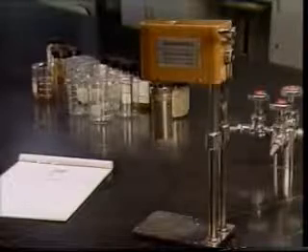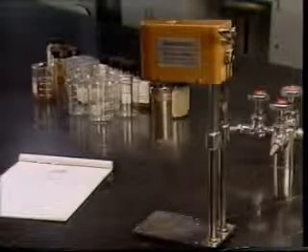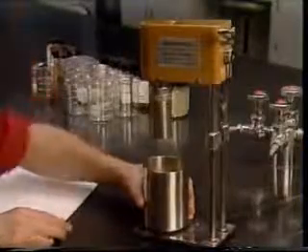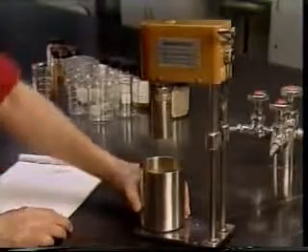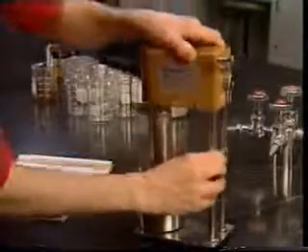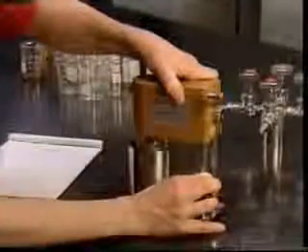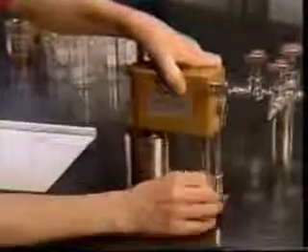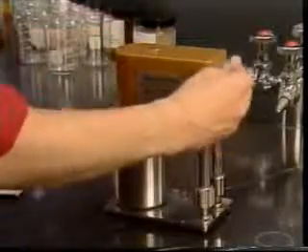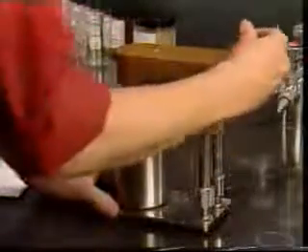First, the test cup is filled to the scribed line with a mud sample, normally the same mud as was used for the funnel viscosity test. The temperature is recorded. The rheometer assembly is raised and the cup placed below the rotor sleeve. Then the assembly is lowered until the rotor sleeve is immersed exactly to the scribed line on the rotor sleeve. The leg lock nut is tightened and the speed shift lever is placed in the agitating position. The crank is turned clockwise for 15 seconds.